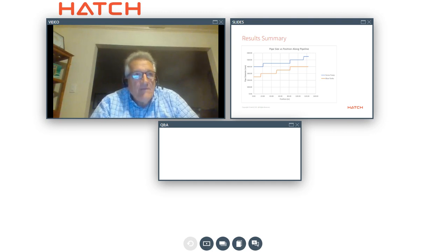So ideally, if we could have a velocity profile in our system that was near to be a straight line, that would basically be a constant velocity system. And then that would really be the best way to mitigate any abrasive wear, because we're always running at the lowest velocity. We can't achieve a perfectly straight line. And you see that the step points, based on the diameters Colin chose, do keep us in that 7 to 10 meters per second range.